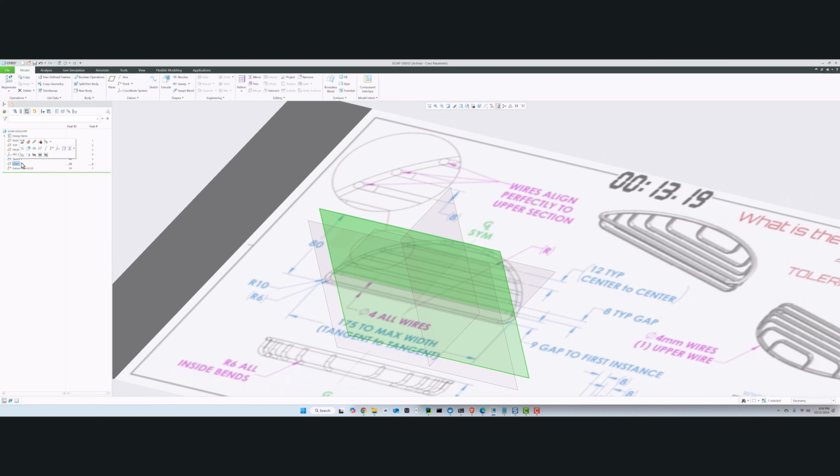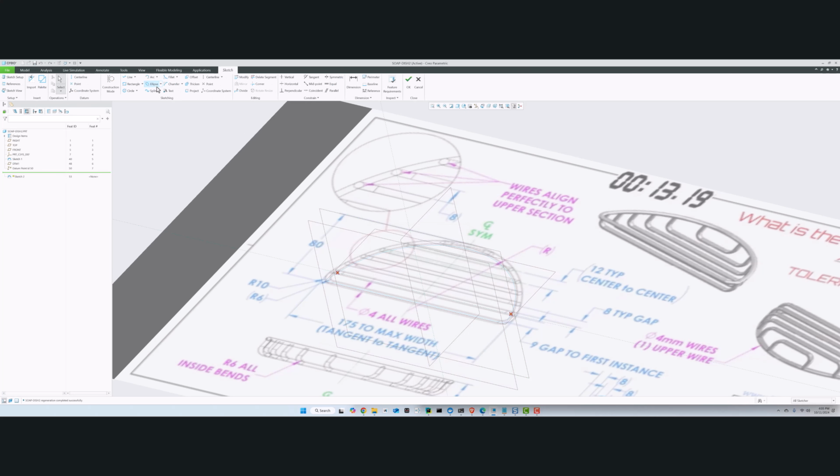So now I've got these very parametric points that I could use. For example, if I go back here and start to move this dimension around, you'll notice as I turn the points on, so you can see them, that those points are going to be moving as that plane moves, giving me this sort of dynamic control, because I'm going to use that next. So let me undo that for a minute, put it back to 16, and we're going to choose that, and we're going to create another sketch.